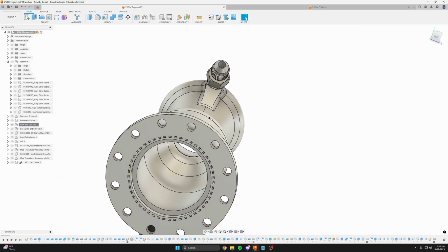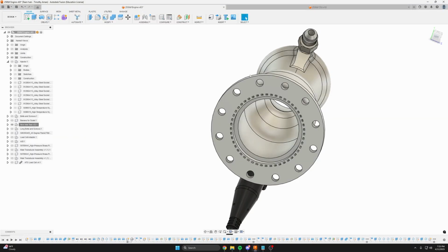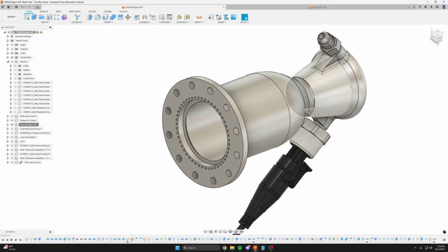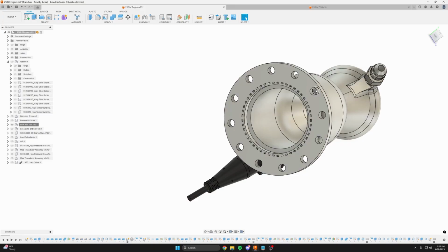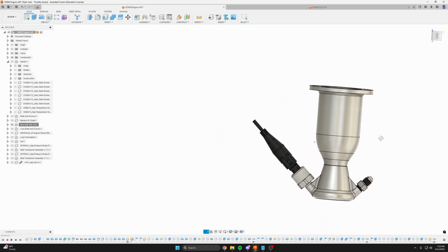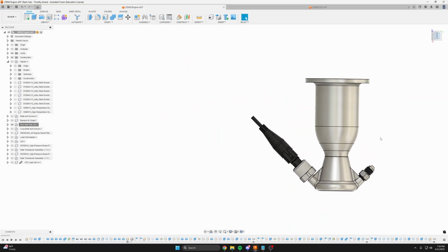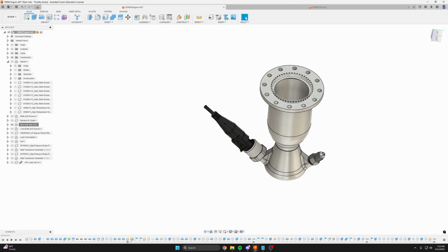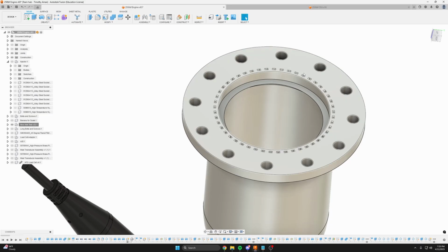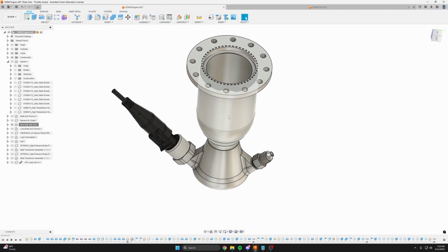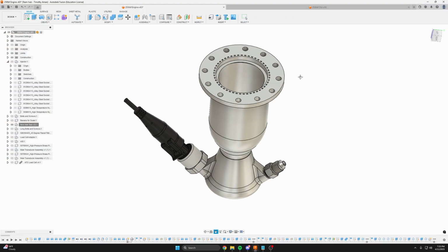That was the kind of channel that gave us the best cooling results in RPA, but it turned out to be very painful to try to depowder these channels for such a small engine. So I'd recommend using bigger channels if you can, if you're going the metal additive route. Potentially printing it nozzle side down instead of flange side down might help. If you can, add some depowdering ports. I've seen a lot of people make a little port off of each cooling channel to blow out the powder, and then you can machine them off at the end when you face it. But yeah, those are some considerations.